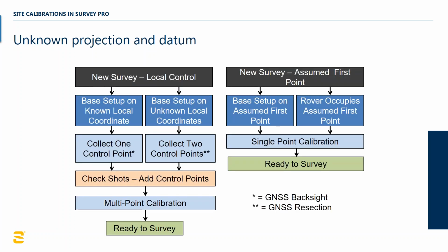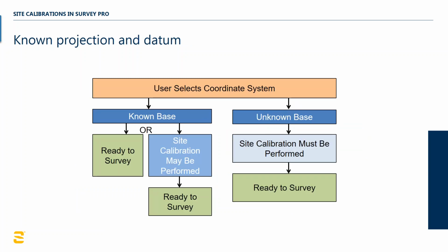And I think a real world example on that one that's kind of simple to understand is, on the left-hand side, let's say the scenario is, like you mentioned, Joe, you got a DOT that's doing a corridor project, and 5 years ago, they put a bunch of iron in the ground and established control coordinates based on a good solution from the VRS, NTRIP provider. And then they're holding those coordinates throughout the life cycle of the project, which might be several years.